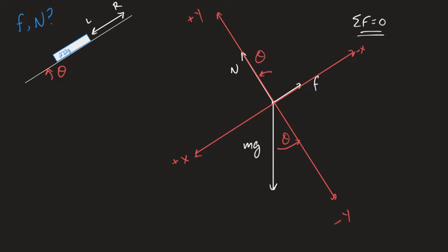Okay, I had a lot of students do this next part wrong, which is why I'm going to come by and check your work now. You have to wrap a triangle around the angle. So this is on you. I want you to wrap a triangle around the angle to break the weight up into its components. It's the only off-axis force is the weight. So please draw in the triangle that you would use to break up the weight. And I do want to see what you do here.